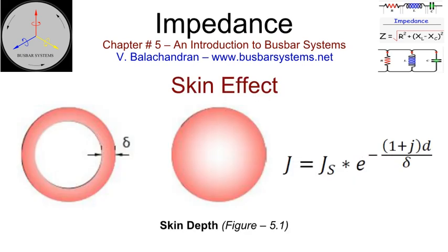Skin effect. The skin effect is the phenomenon that concentrates the flow of an alternating current nearer to the outer surface of the conductor. This phenomenon is much easier to explain with a round conductor, though it can be extrapolated to any profile. The current density will be maximum at the outermost surface, or at the skin, and reduces as the distance increases from the surface to the center. The variation in the current density will depend upon the resistance or resistivity and the frequency, the rate of variation. The effect will be more pronounced with increasing frequency and lesser resistance.